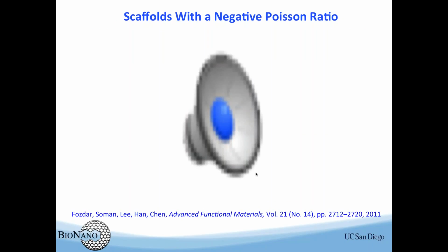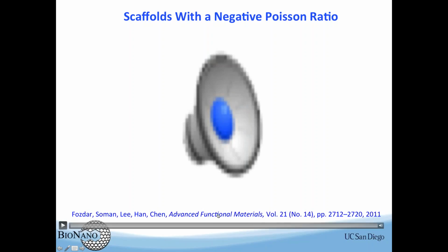Another mechanical property is called a Poisson ratio. You can do a quick experiment when you stretch a rubber band or other soft materials. You can see that you can make it longer, but then in the z direction, in the y direction, this material becomes smaller and smaller, and eventually will break. Right. So I would say 99.9% of the material behaves like that. We call it positive Poisson ratio. When you stretch them, they become smaller.